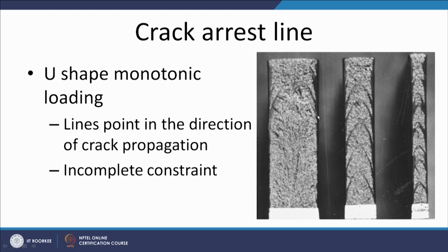So, the presence of these marks indicates that incomplete constraint exists. Here the situation is nearer to plane stress condition, and as the thickness increases we approach the plane strain conditions, but still if these marks are present, that will indicate incomplete constraint.